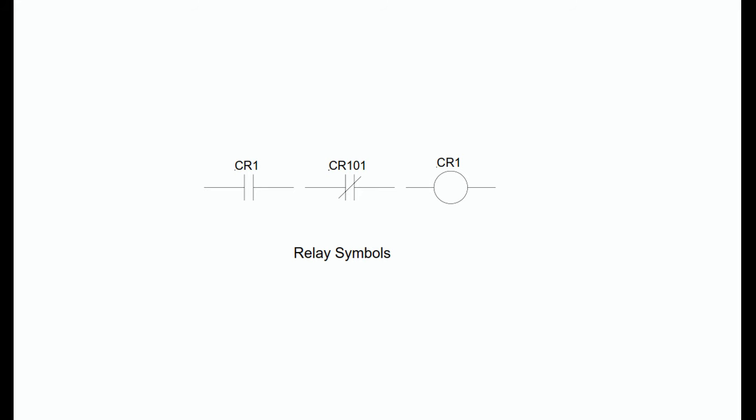These three symbols are a normally open contact, normally closed contact and coil. Notice that the normally open contact on the left could easily be misconstrued by an electronic designer to be a capacitor. That is why it is important when working with electrical machines to mentally shift gears to think in terms of electrical symbols and not electronic symbols.